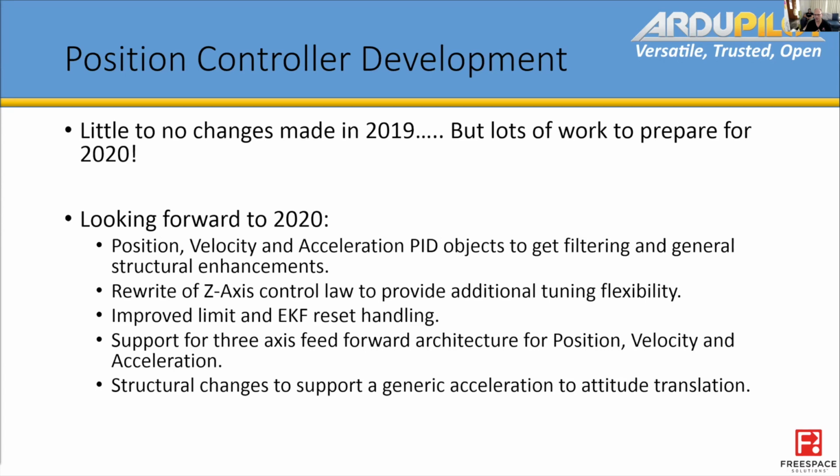In particular, the Z-axis control law has a few hard-coded aspects to it, which make certain problems difficult to tune around, so that'll be a nice relief. But it will also open up alt hold and position control, the position control PIDs, to potentially be auto-tuned as well.